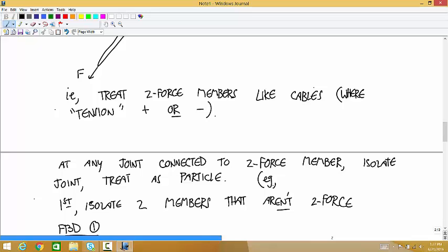Okay. So what if you have two forces acting at the same point on one end and on the other end you only have one? Is that still a two-force member because there are still only two directions acting at the same point? Say it again. Like when we had a couple connected, for some ends we might have two forces, but they're still acting on the same point. Yeah, in the same direction, that's right. But then we have another one that's acting opposite. Are those two forces and this one force still considered a two-force member? Yes, because any forces that act at the same point, you can lump them together, and it's a single force vector. Yep.